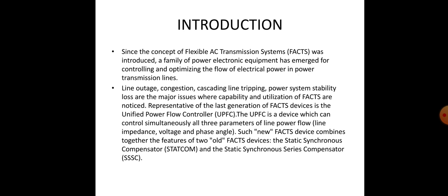This UPFC is a device which can control simultaneously all three parameters of line power flow: line impedance, voltage, and phase angle. Such a new FACTS device combines together the features of two old FACTS devices, that is the static synchronous compensator STATCOM and the static synchronous series compensator, that is SSSC. This UPFC was first proposed by Gyugyi, and it is the most versatile FACTS controller for regulation of voltage and power flow in a transmission line.